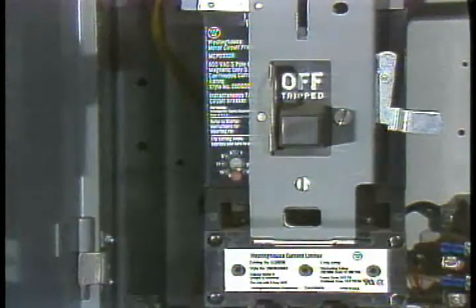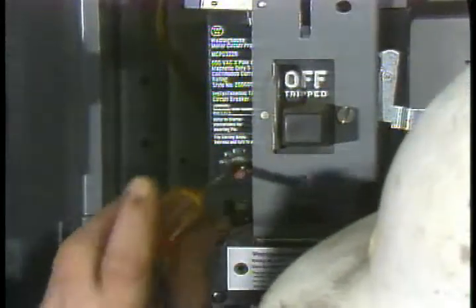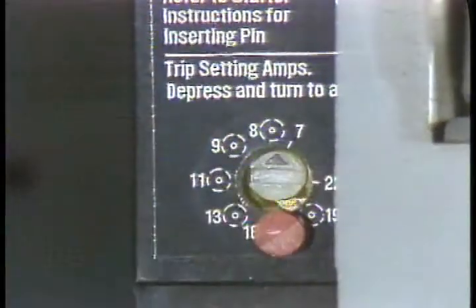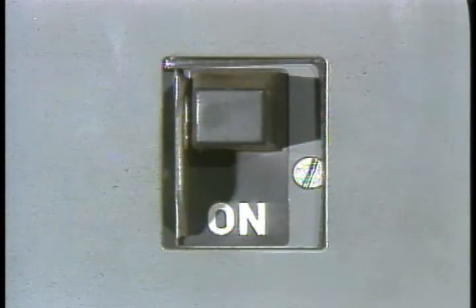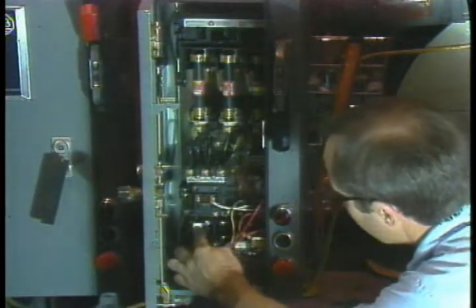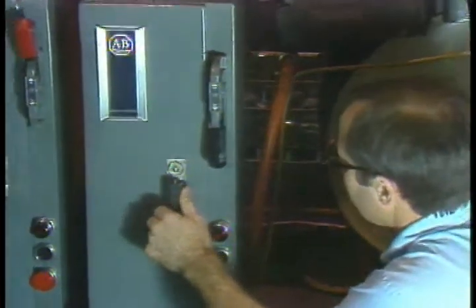Installing and connecting a motor requires careful attention to the setting of the overload breakers. They monitor the current to the motor and trip open when current is more than rated full load current for too long. Their purpose is to prevent a motor from burning out under overload conditions. Troubleshooting a motor often means detecting when a motor is overloaded and locating the cause.